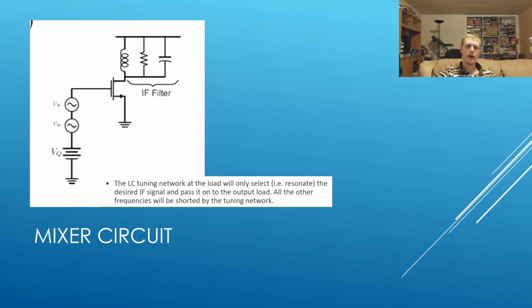It is not good practice to add the three signals together by putting them in series, because connecting transistor circuits in series breaks the circuits. One way we can combine these is by using a transformer. The magnetic fields from the three input signals would be used to induce an output signal at the transformer output. But this is not how they are combined in a cell phone. It is a much more complex circuit which we will not be covering.